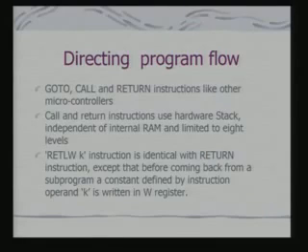And if you see these program flow control instructions, goto, call and return, the call and return instructions obviously use the hardware stack, which is independent of the internal RAM and is limited to 8 levels. So even if you consider a hypothetical scenario where there are no external interrupts, you still cannot have arbitrary nesting of subroutine calls, because your maximum depth is fixed.